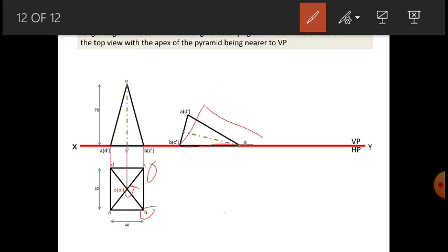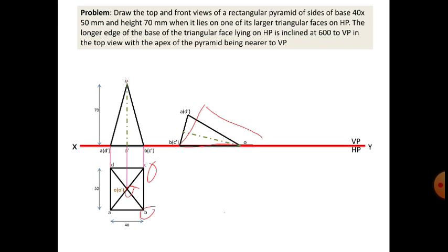Once you make it rest, project these lines from the rested object, from the HP object, and project them below and get its top view.